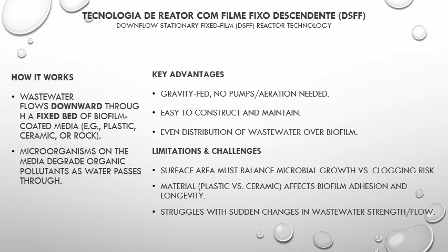Also, we do have the downflow stationary fixed film reactor technology called the DSFF. How this works is wastewater flows downward through a fixed bed of biofilm coated media like plastic, ceramic or rocks. Microorganisms on the media degrade organic pollutants as water passes through. What are the advantages of this? It's gravity fed, meaning no pumps are needed, no aeration needed. It's easy to construct and maintain, with even distribution of wastewater over the biofilm.